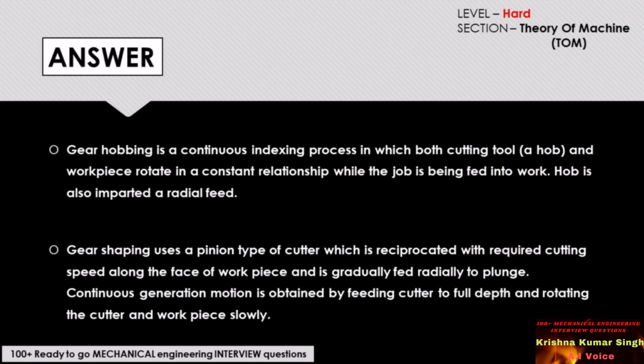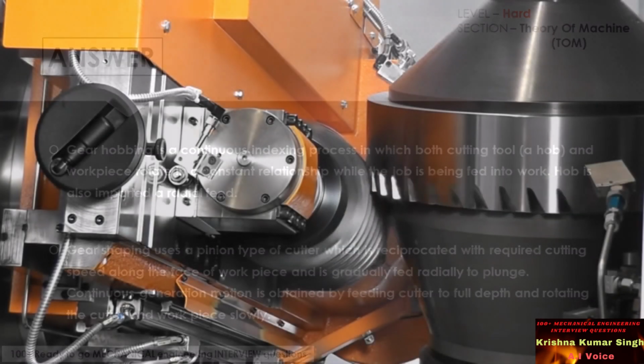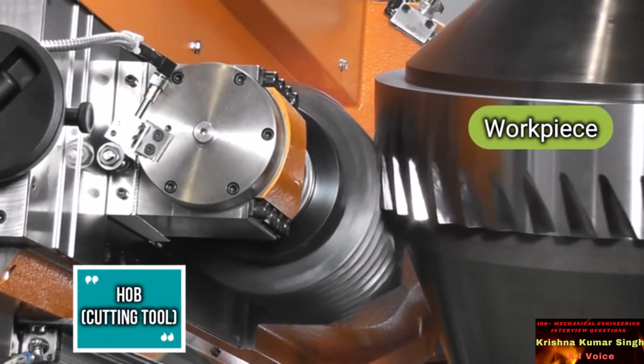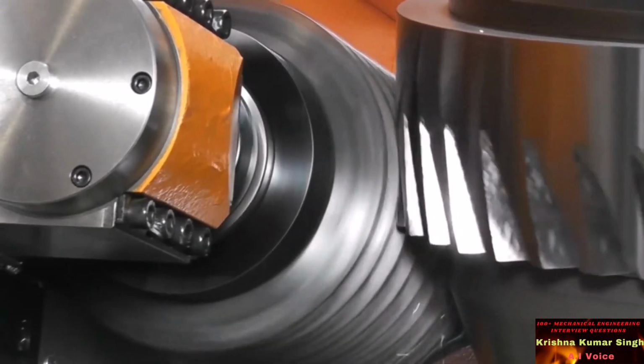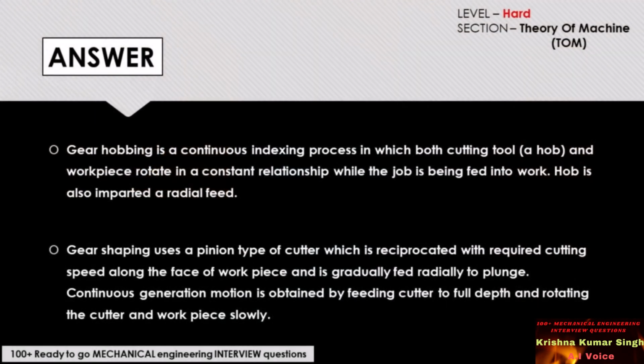The answer to this question would be gear hobbing is a continuous indexing process in which both cutting tool, that is a hob, and workpiece rotate in a constant relationship while the job is being fed into work. Hob is also imparted a radial feed.